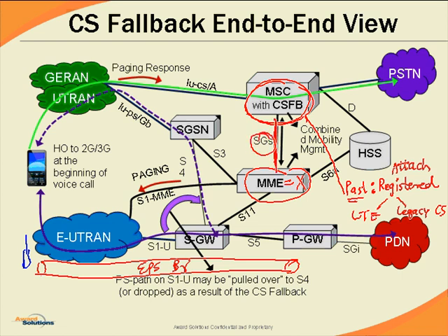So when we did the power up, in the LTE coverage area, then we did the attach operation with the LTE, and at the same time, we had communication between the MME and the closest MSC, who is in charge of that geographic area. So we have communication between MSC and MME.